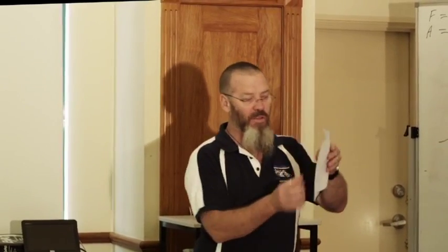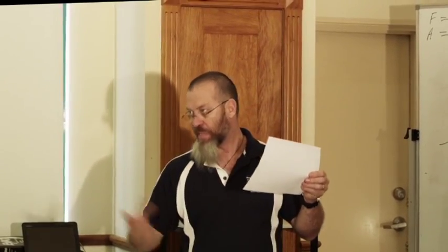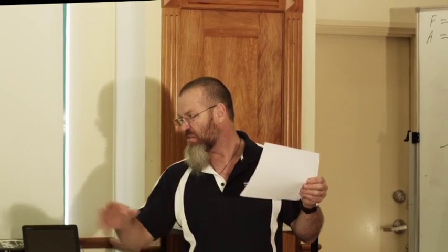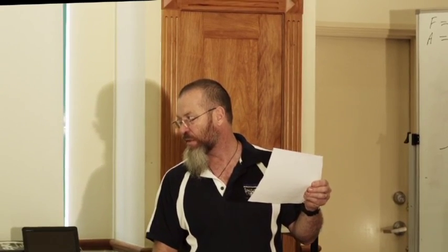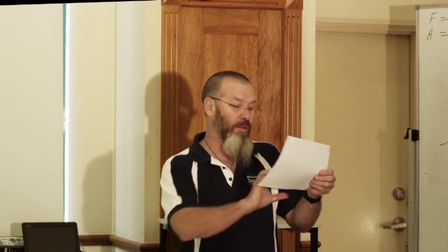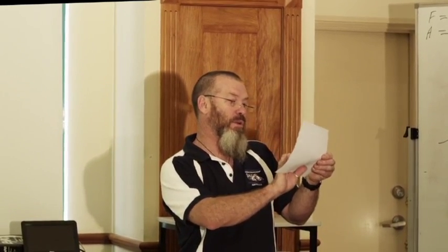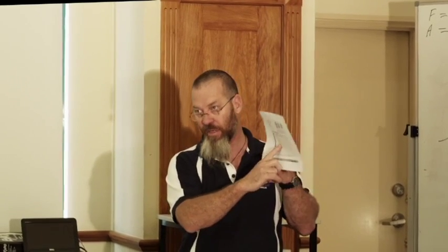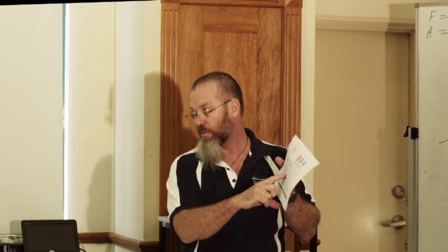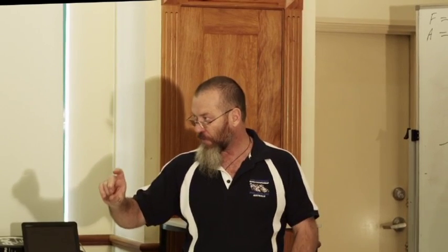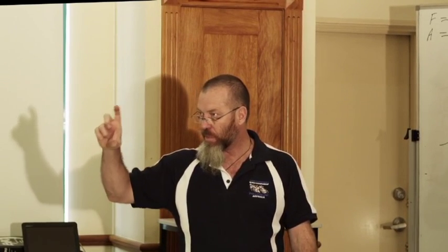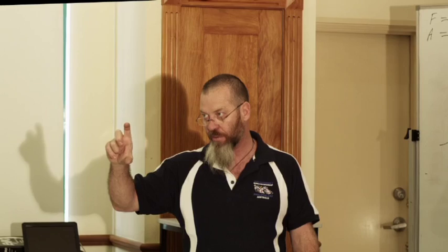Now, on this one, M10 Dynabolts, generally used to tie down wall frames, aren't they? Would you say that, or M12s? M12s, okay. First of all, an M12 Dynabolt should have an embedment depth into the slab of at least 55 millimetres. Okay? 55 mil, 45 mil frame means it's a 100 mil Dynabolt.